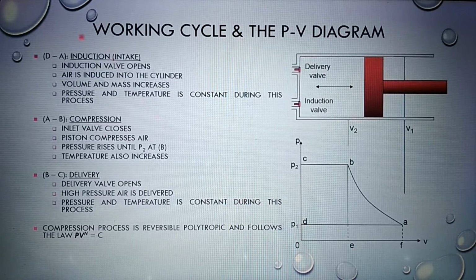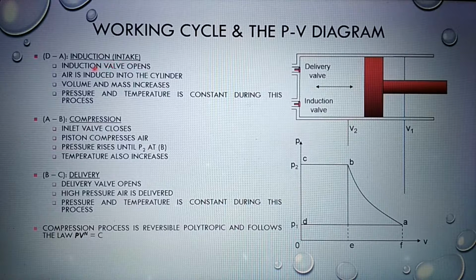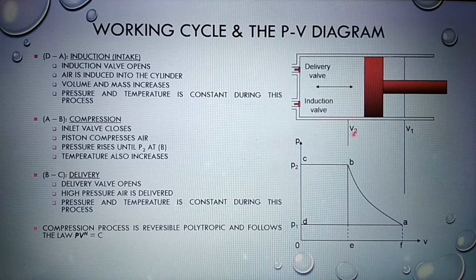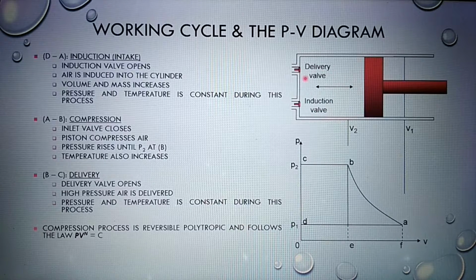Now I will explain the strokes involved in the reciprocating compressor. For the induction stroke or intake stroke, the induction valve opens as the piston moves from point V2 to V1. This motion allows air to be induced into the cylinder, causing the volume and mass in the cylinder to increase. The pressure and temperature remain constant during this process because the induction valve is open.